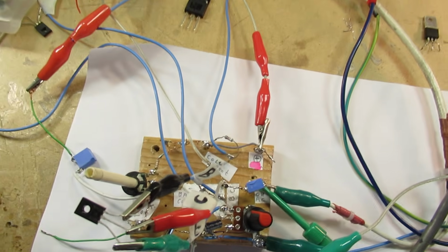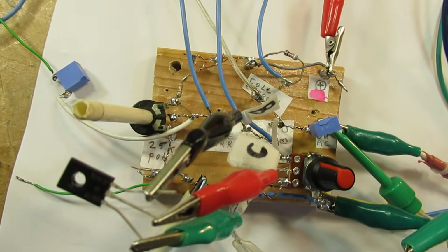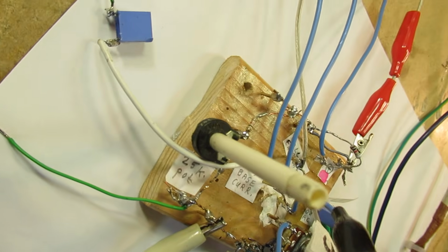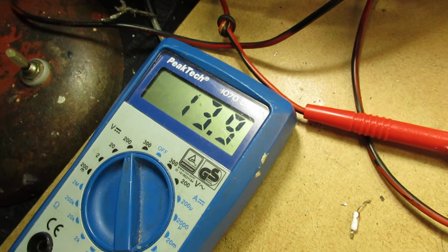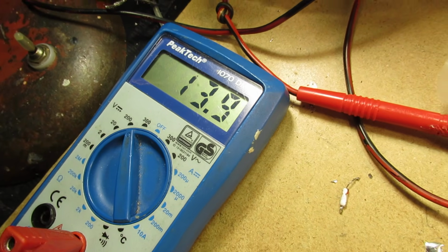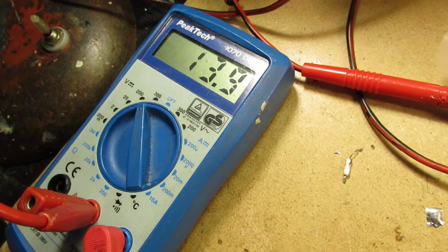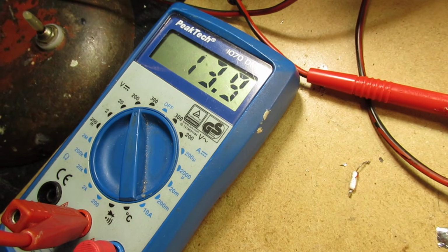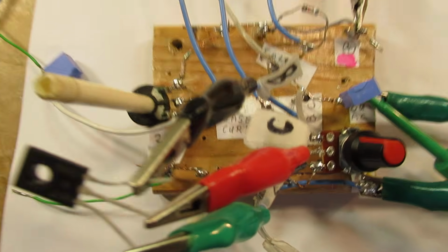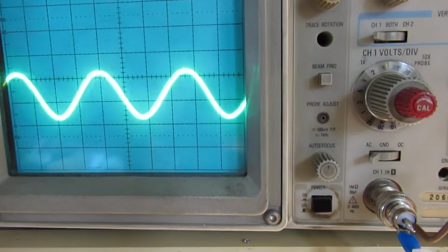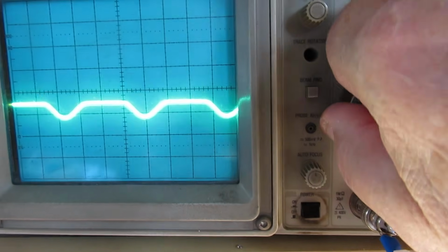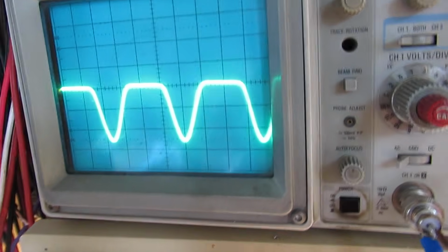And let's see what happens when we change the bias here with that 25 kilo ohm potentiometer. Working at the moment on 13 volts, 14 volts. Important to tell that I could not find any difference in noise for voltages between 6 volts and 18 volts. Anyway, so change the bias. Let's see what happens. Of course, at a certain moment it doesn't work okay any longer.